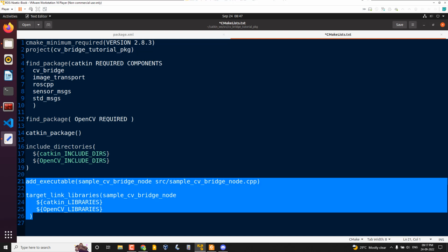So it's our duty to write optimized code so as not to use the complete RAM. If you are running nodes consuming 3.8 GB out of 4 and you are trying to operate the robot, after some time there can be issues, because the robot is continuously working and the RAM usage can accumulate.